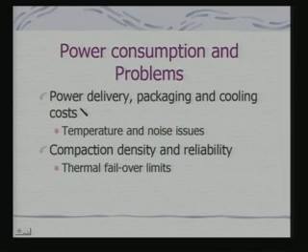So, what are the power consumption problems? In fact, there are the power delivery, packaging and cooling costs, and as the temperature increases, the effect of noise also becomes more dominant. So, it will always be desirable to minimize power consumption. This also has implications in terms of compaction density and reliability, because there can be spots which may be heated on the chip itself, and that may lead to failures.